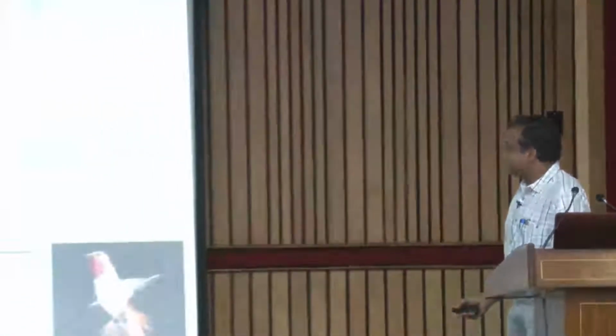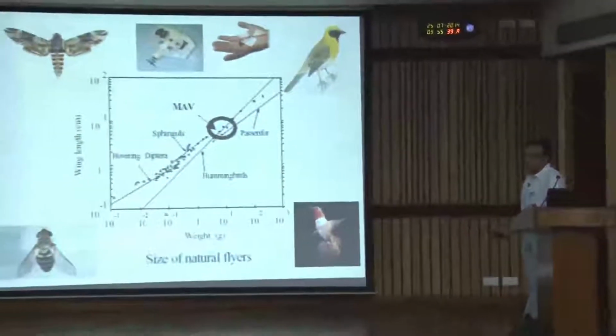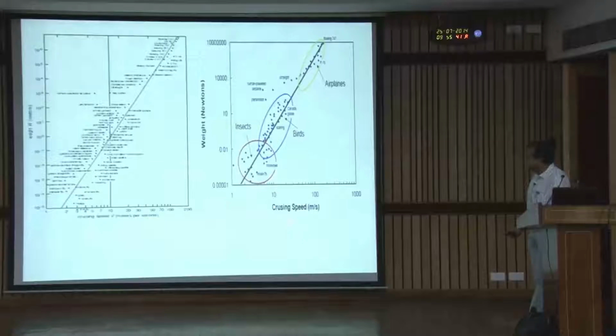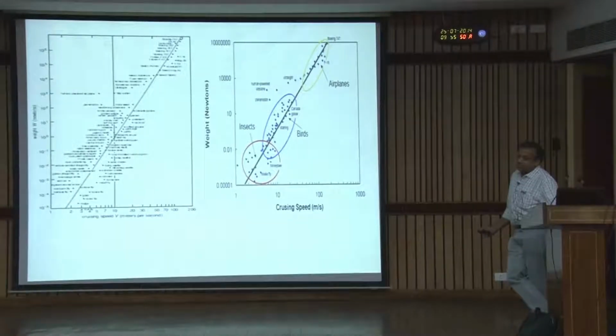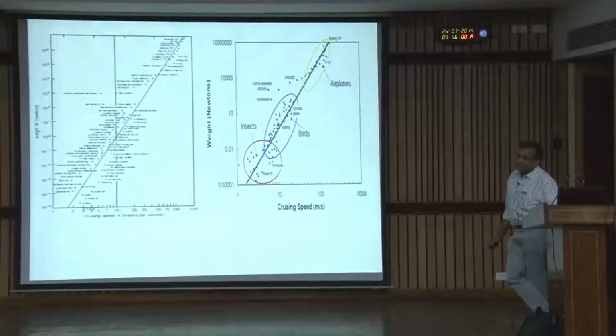See, that is some guideline. You are talking about these graphs. This is mass versus velocity. And this is energy consumption. Weight versus wing length. There is no energy consumption. This is cruise speed versus weight. So this gives you the size restriction. The power estimation you can do once you design a model; you can use that theory and try to get a power estimation.